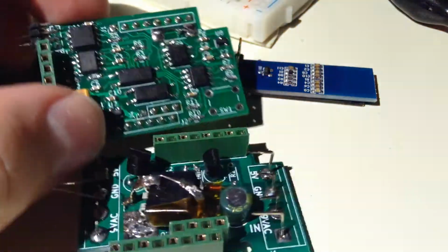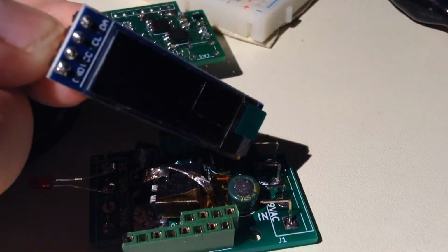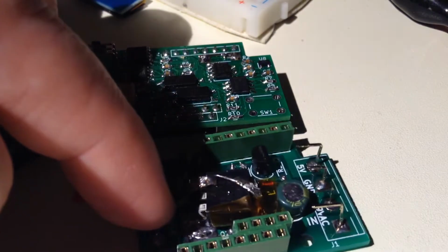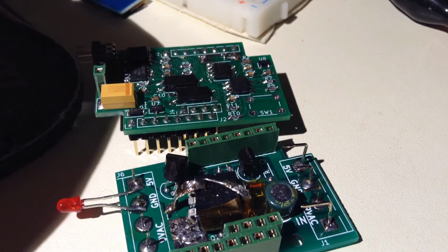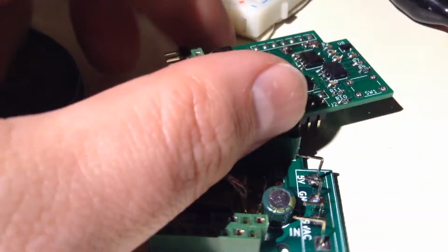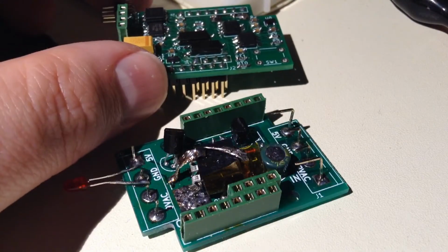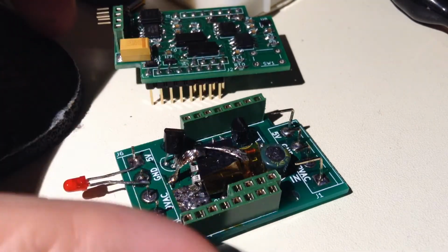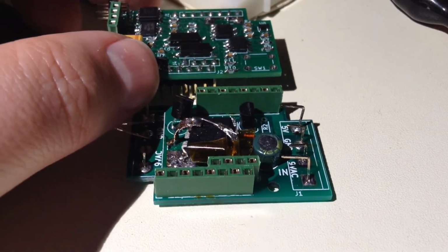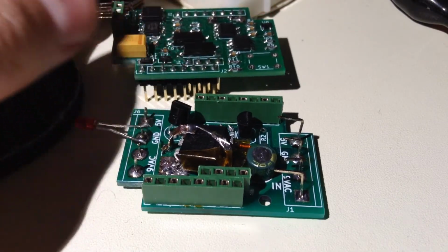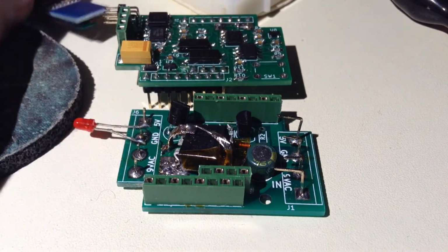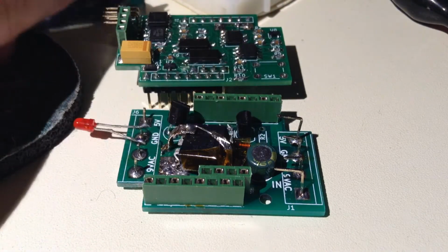Also, the second thing I want you to be able to configure here is, if there is a fault, you can select if it wants to auto reset or not. It keeps the output low even though the voltage comes down again. The reason for that is sometimes you get power supplies with dry capacitors, then there will be like a 50 Hz thing and it will switch on and off very fast. It's not dangerous, but well, you can detect that. Maybe I can make an algorithm that says something about that on the screen.